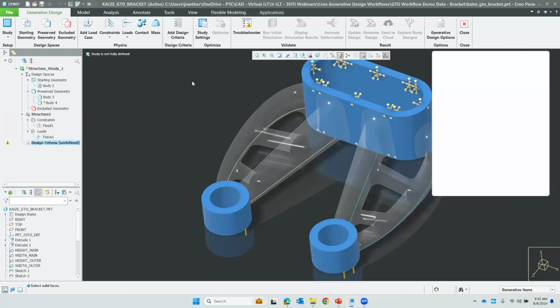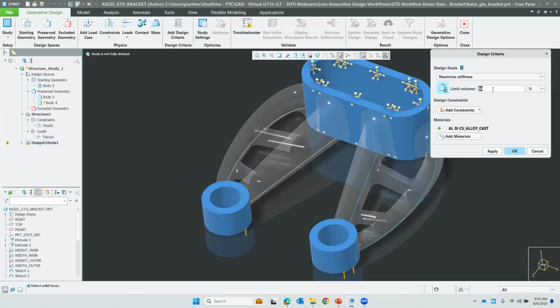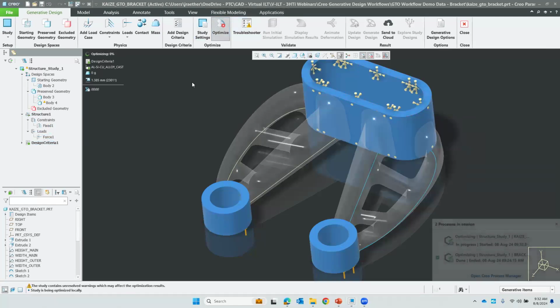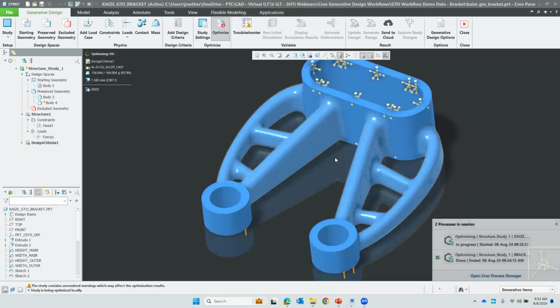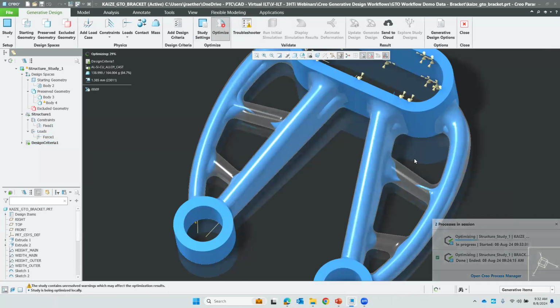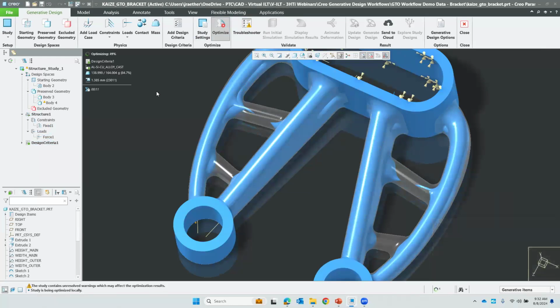Now we take this. Here's where we're playing with the limit volume. Right? Now I'm going to say, hey, let's just back off the limit volume. So at 85%, show me what areas are most important. So very quickly, I'm going to take a model, look at it, do the analysis, and just by playing with the limit volume, I'm going to be able to see in my model what is most critical.